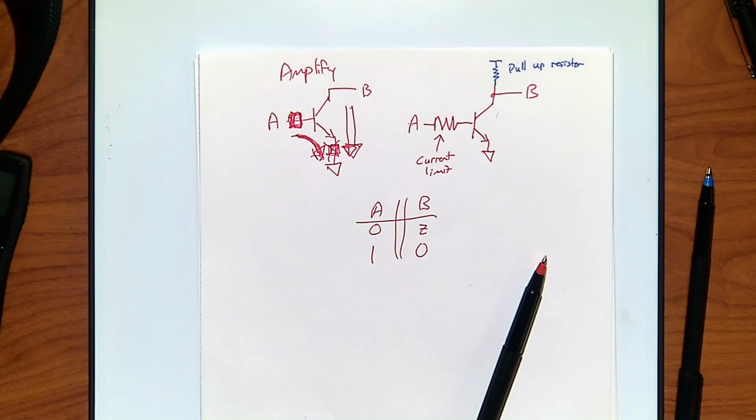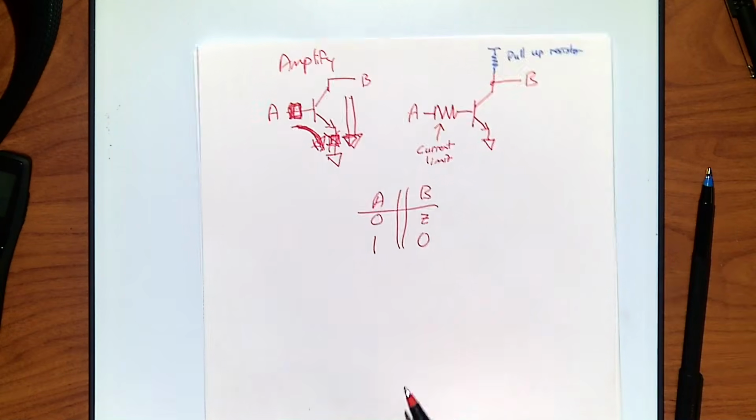So what is this? It's an inverter, but how much current and how good is the voltage coming out of this? Yeah, so it's strong. It's coming from the source just through a resistor to limit how much flow there is. So this is now strong. It's been amplified. So this is an inverting amplifier. Yay! All right. Cool. We've got an inverting amplifier state.